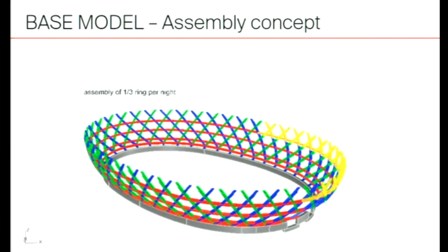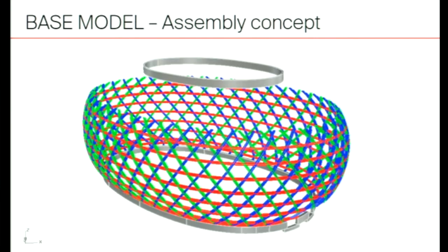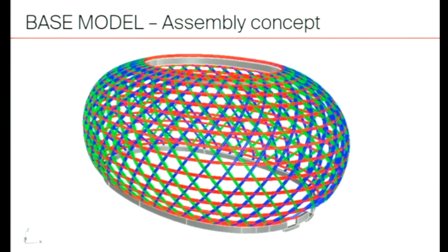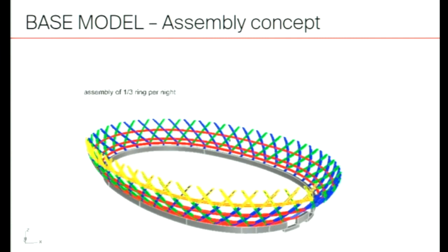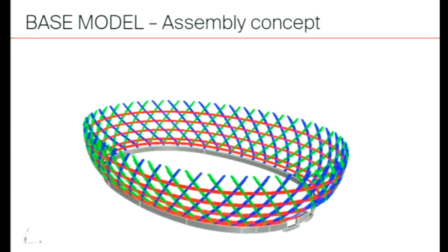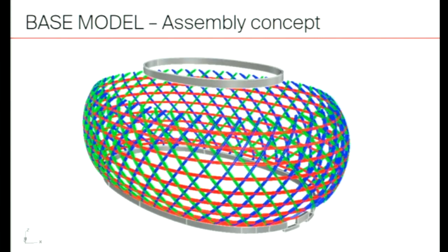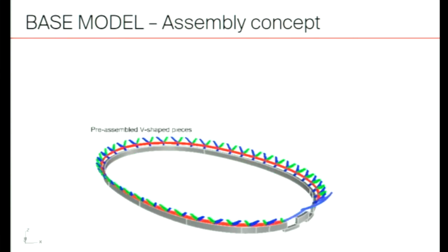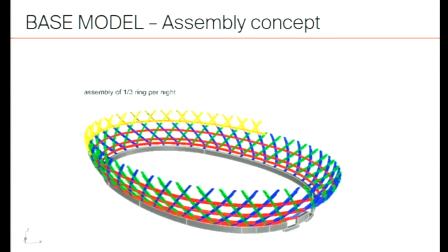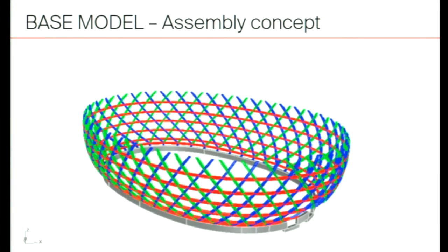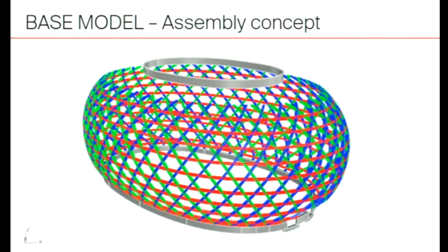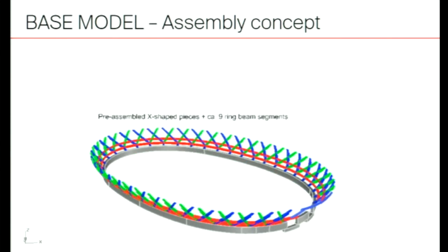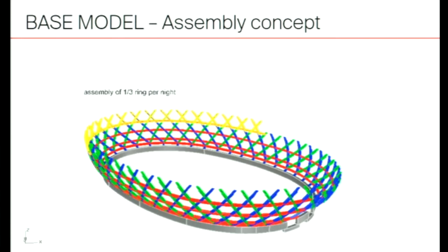And the timber structure is designed to be self-supporting from the very beginning of the erection process. So the levels are added horizontally one after the other, using very few punctual supports, which allows us to save the cost and space of the scaffolding, and that's always good news when you're working on a narrow island, which is turned into a massive construction site. Additionally, the entire structure was mounted using the only available crane outside and during nighttime, since it was used at daytime for the concrete work.